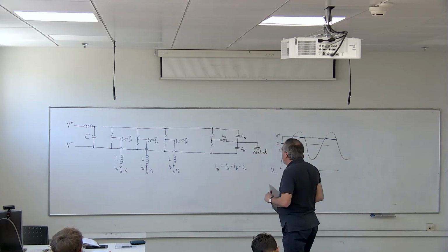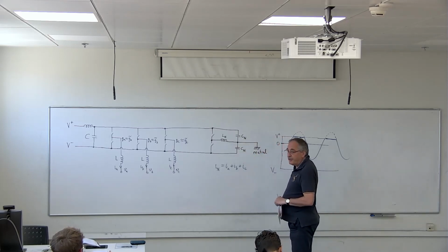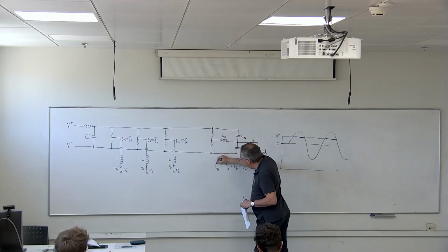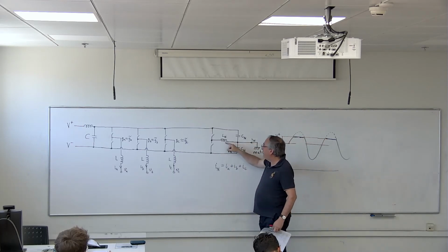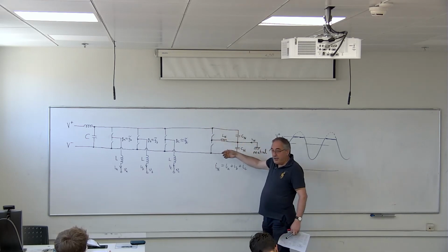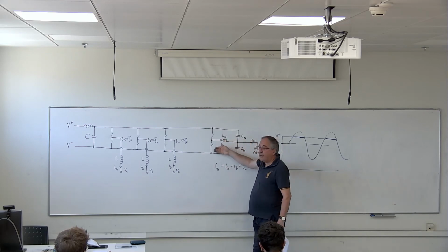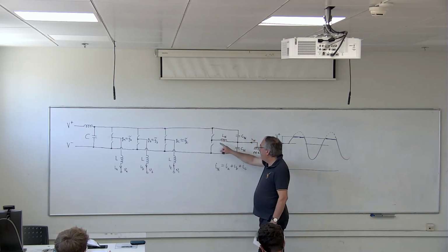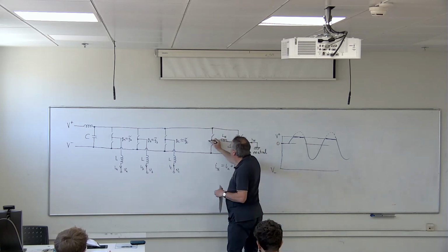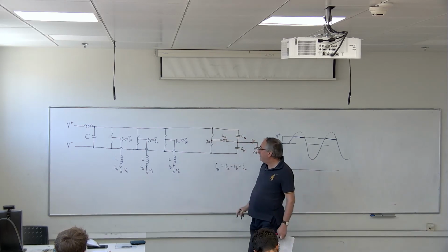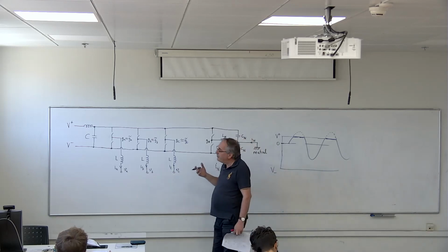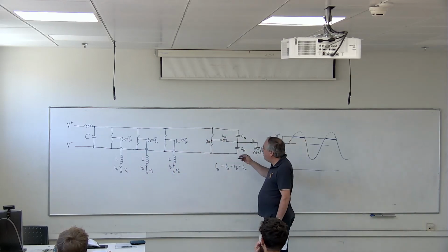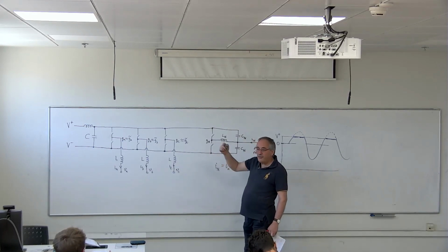Now, what is the advantage of this circuit is that you can have, if you need it, a neutral current here, IN. So this neutral current comes now here, and it flows into a canonical switching cell, and there is no limitation. It can be a very big current flowing into the canonical switching cell, and you try to control the canonical switching cell so that the average voltage here, let's call it Gn, you try to keep Gn equal to what you call 0, the average between V plus and V minus. Let's say that's your definition of this. So you keep this Gn at this 0, which is the average between V plus and V minus.